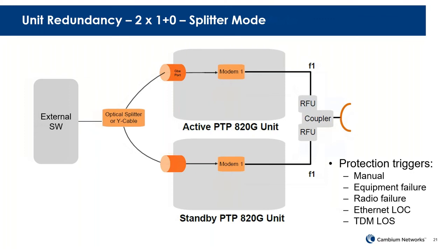Let's say if you happen to choose to have multiple Ethernet ports turned on, but only one Ethernet port from each radio is being used, then you need to disable the Ethernet port that's not being used. Otherwise, there will be an alarm complaining that the Ethernet port has a LOC, loss of carrier. And because of that, the radio will not be able to fail over properly. So very important, when everything is done with the installation and configuration: no alarms, no alarms. Super important.